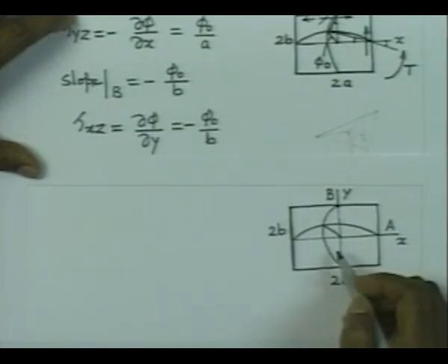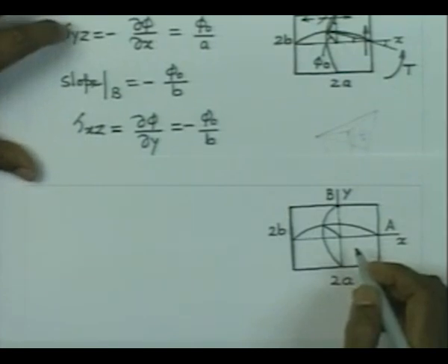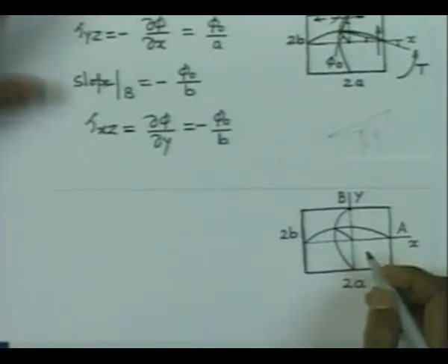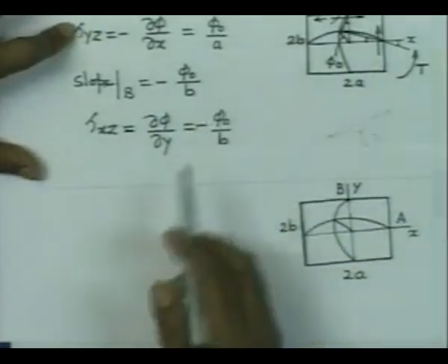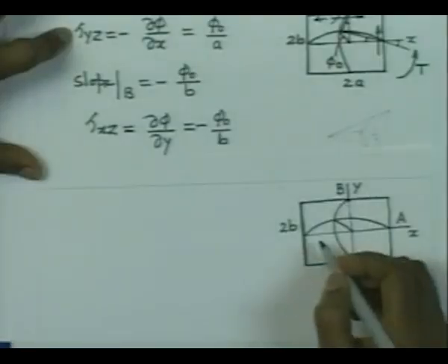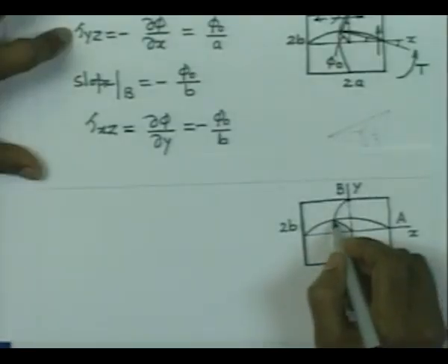It is different from the circular cross section, wherein you have found that the stress is going to be highest at the furthest point. We would like to do a little more calculations to see the value of these stresses in terms of the applied torque. So this doubly curved surface that we were talking about, let us approximate by a pyramid.